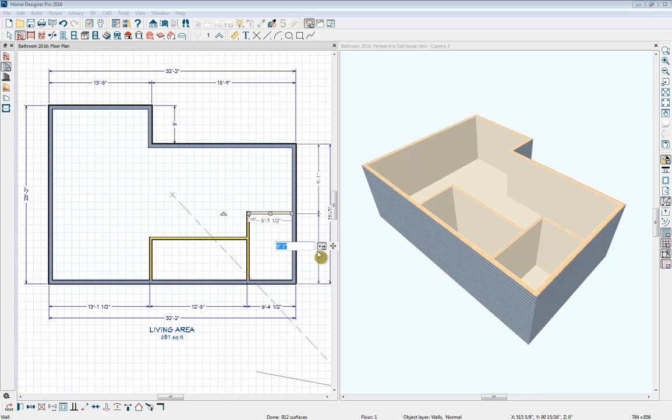So I'll just use our auto exterior dimensions, and we'll do 8 feet 10.5 inches. So you can use decimals when you're typing these in. You can also get into fractions. So for instance, we'll do 6 feet 4 7/8. So you can do fractions in here as well.